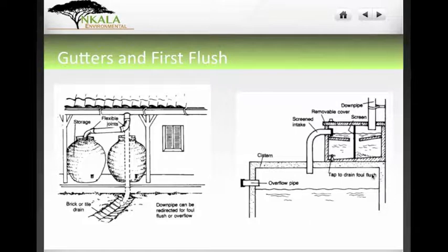So again, you still have to drive, right? None of this stuff is automated where you can set it and forget it. You still have to be very much a part of your system. When it stops raining, you have to make sure you empty your first flush box and close your valve back, and you have to be very, very active in it. So that's very important, and it helps to keep you involved in the maintenance aspect of it, which becomes very important.